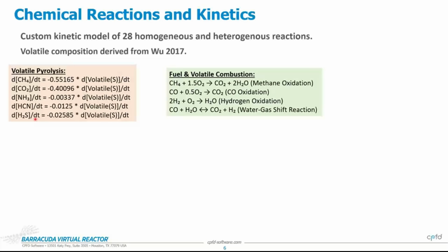Once they come out, then you have this volatile combustion that takes place, right? So your methane reacts with the oxidizers. So you have methane oxidation going on, CO, hydrogen, and water gas shift reactions that take place, right? All of this, again, remember, is taking place simultaneously. It's not a staged thing as I show in this picture. This is more to break down what's happening inside the reactor here.